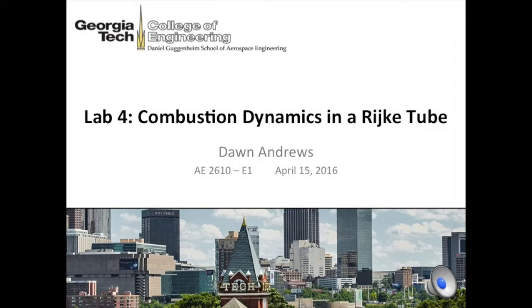One last possible source of error could be that the Rijke tube was struggling to take in enough air to maintain a flame. We placed a fan underneath it, but the fan's oscillations partially transferred to the pressure fluctuations in the tube. Despite all this, the results do follow the correct and expected trends, and the experiment was successful in demonstrating combustion dynamics in a Rijke tube.